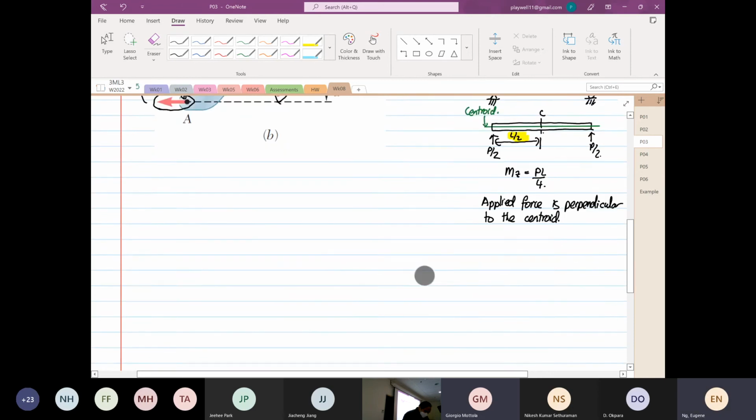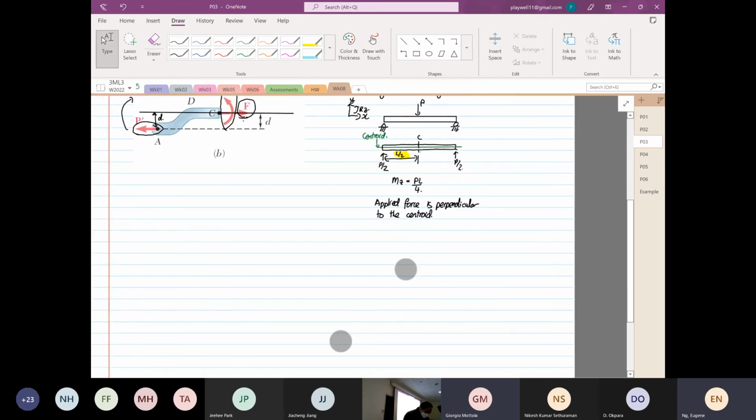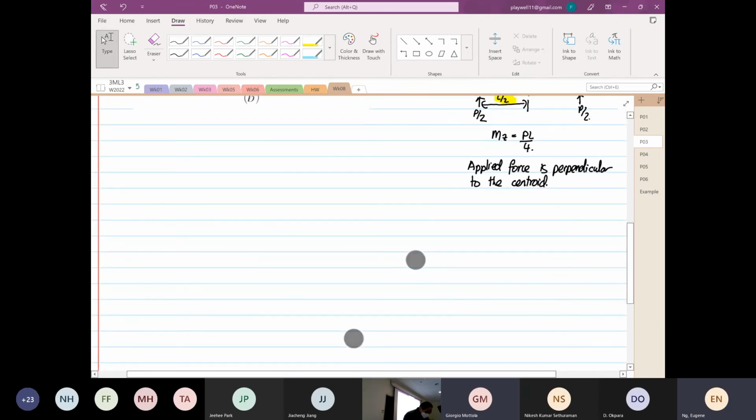We are aware that this has two components in the equation. We know that stress x is equal to Px over A, plus Mz over Izz multiplied by y.